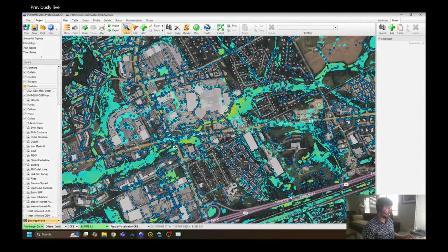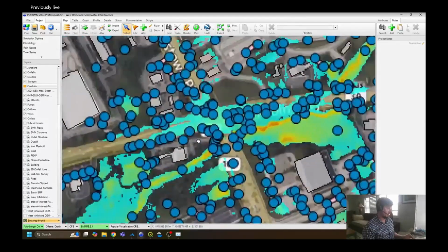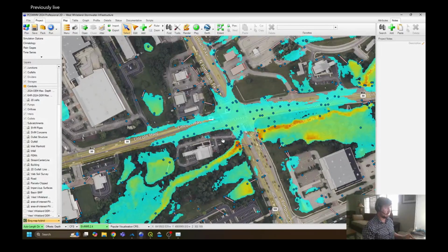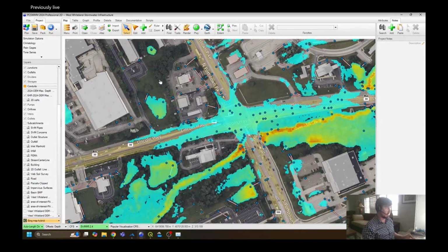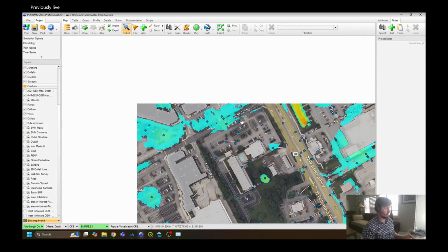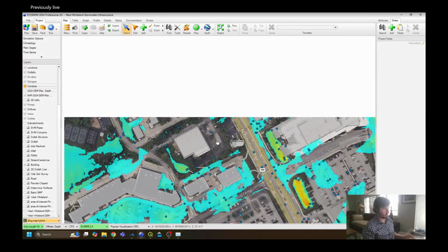But especially when we get to these downtown areas, if I'm not taking into account things like the catch basins on the street, so this is actually a spot that floods during major storms in the town, this intersection. But especially if I run out the model in time, we'll see that these catch basins are actually really helping to drain down a lot of these pockets of flow or of inundation that wouldn't be able to be taken into account in a purely 2D model. I need to have these 1D elements in order to see what's going on.